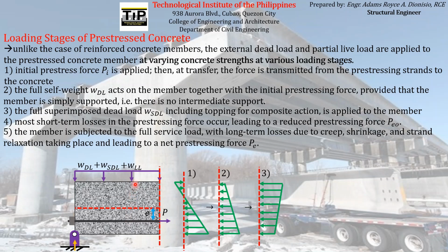And if you add those flexural stresses to this current stress diagram here, the resulting diagram will look something like this. You can see that the trend on the extreme bottom fiber tends to have lesser and lesser magnitude until it becomes a tensile stress.